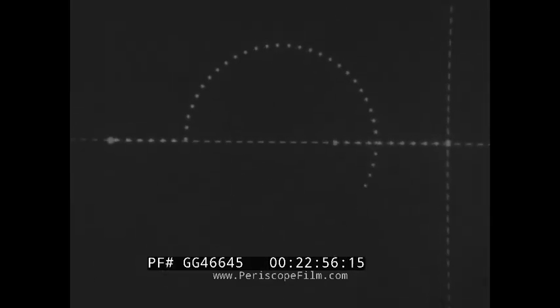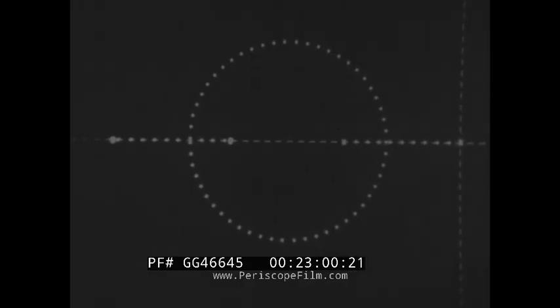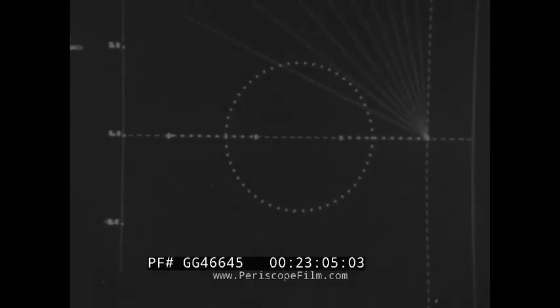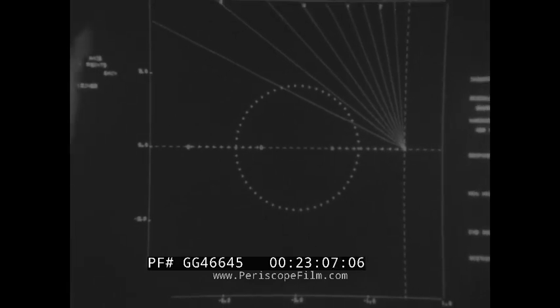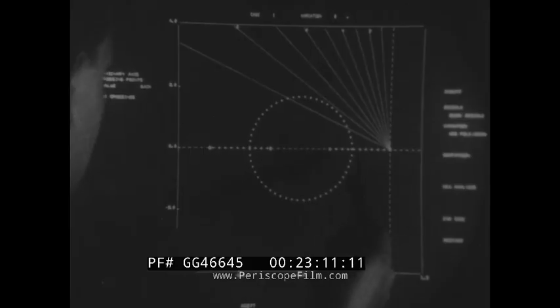With this plot, we get a clear indication of the effect of gain adjustment on the stability of the system. To get quantitative information from this locus, I choose any point on the plot, and the program returns to me the exact position of that point and the gain and damping ratio there.